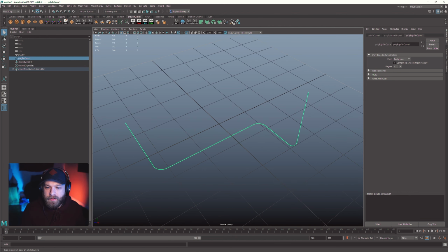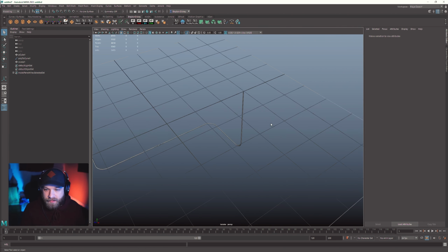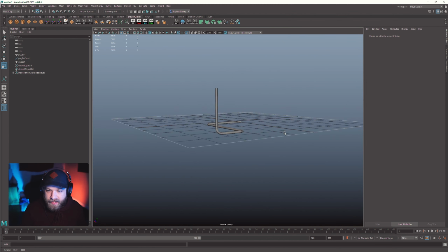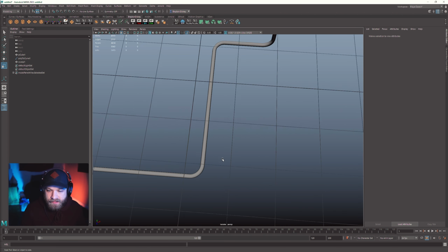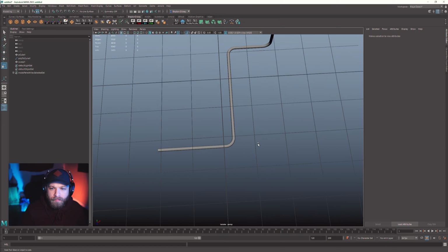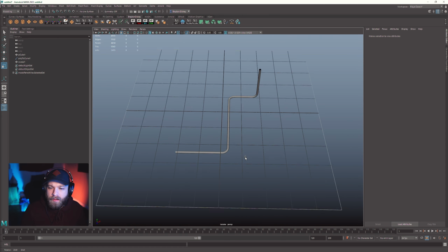And now if we do the sweep mesh tool here, and make sure that we have isolation on. Okay. Now you can see that if I up the curve here, it has made us a perfect pipe structure that is exactly where we had that edge. So you could use that really quickly to make a more complicated pipe structure.